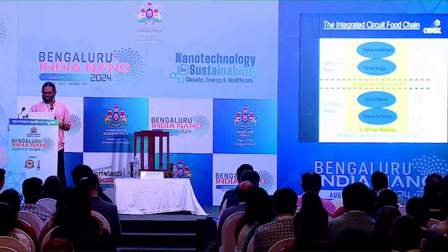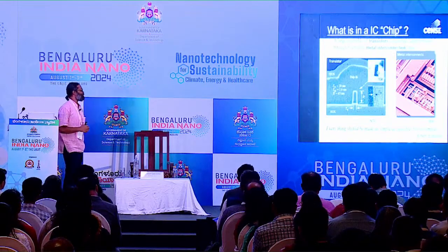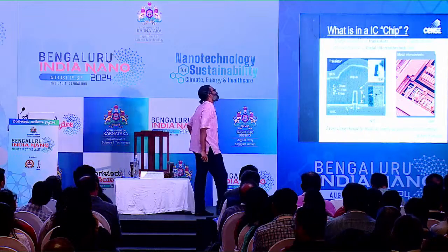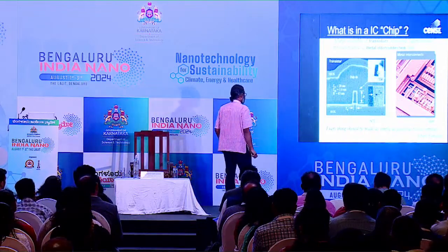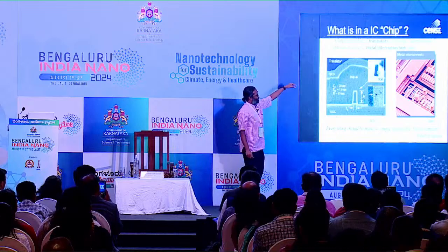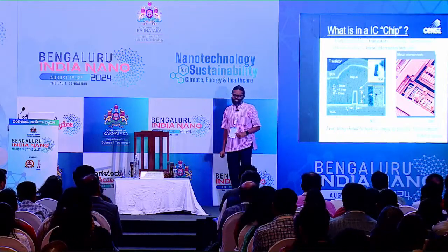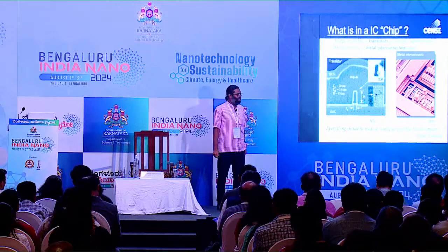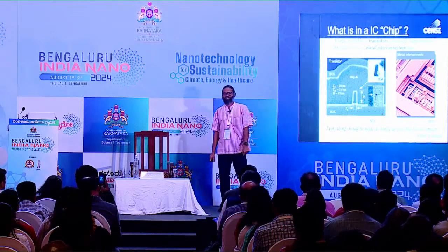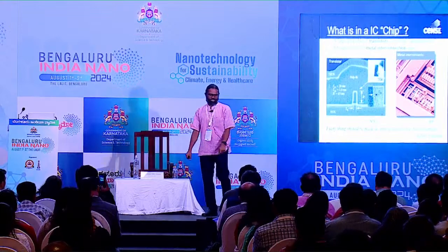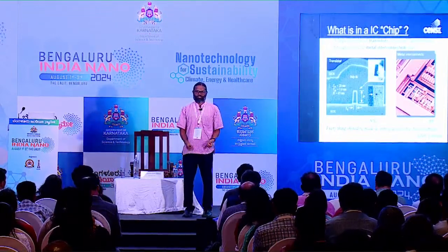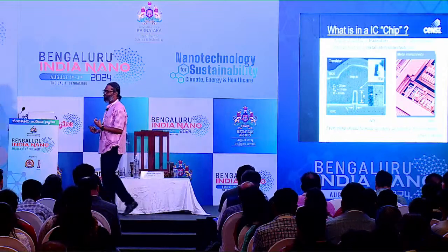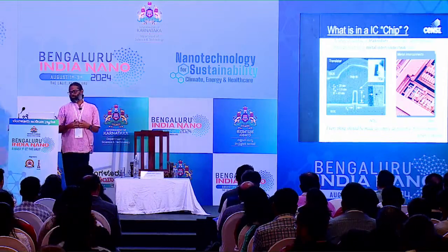So what are we looking at? We are looking at two things. One is the transistor, okay? On the left side, you see this is a very old image from Intel, right? The thin wires, the bright spot that you see, that's actually the gate, right? So that's one transistor. And what you see on the right side is actually the copper lines that are connecting the transistors. So these two are the essential ingredients to make any circuit, all right?